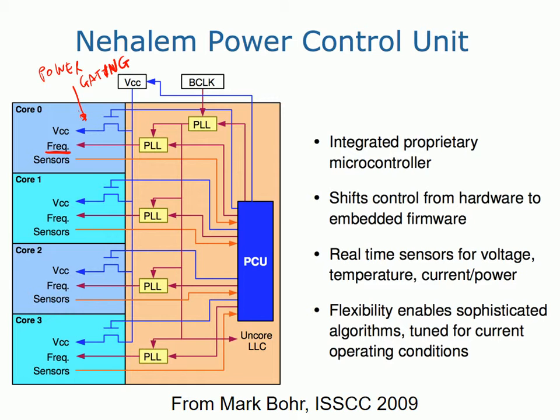And in modern microprocessors, you typically have a control unit that, depending on the load on each single core, adjusts both the clock frequency and the supply voltage to the load, so that if you're able to reduce the supply voltage, you can significantly reduce the dynamic power consumption. Okay, so you have basically 3 different degrees. If you do not need one core, you switch it off. If you need a low load, you decrease the clock frequency, reduce the supply voltage so that the core can go slow and therefore have a low power dissipation.